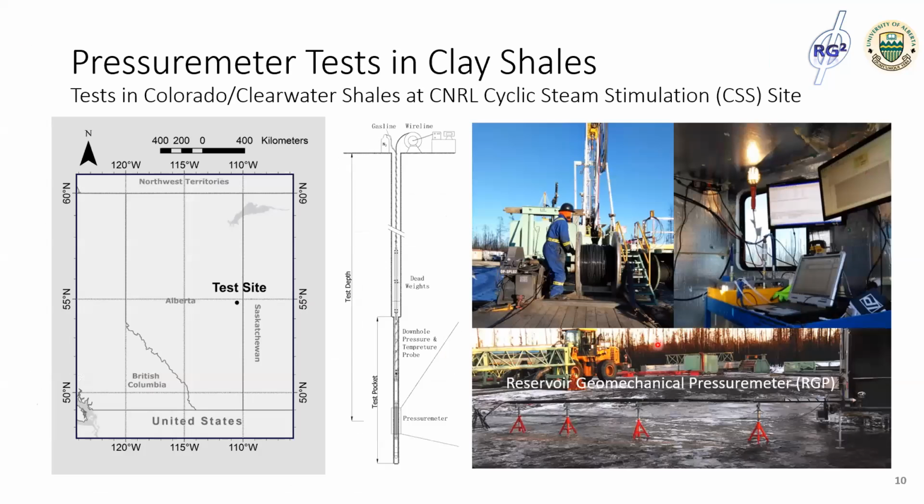So Pressuremeter testing is different from the other testing because it does not only provide results from a point load, like the CPT or SBT, where you just push the tool through the ground. Pressuremeter testing is conducted in a way that the full stress and strain curve can be obtained. So it does not only provide information at one stress condition, it provides information on the constitutive behavior of materials along the stress path.